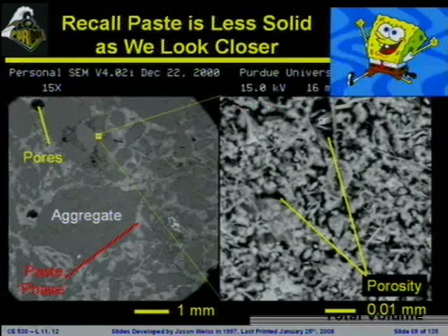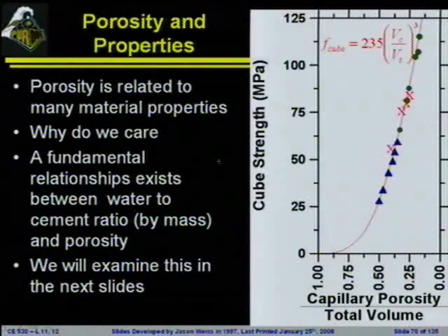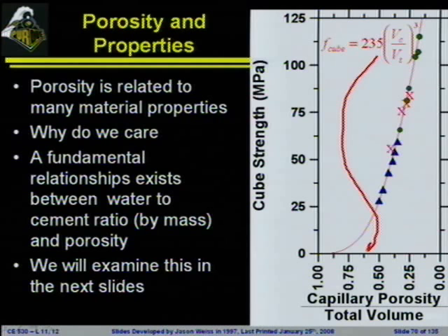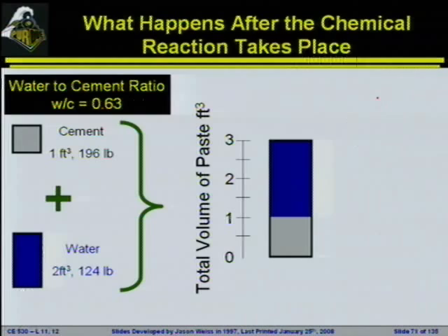porosity. All right, so we're remembering that everything is porous, we're remembering porosity is going to be related, and we're remembering that the strength is related to the volume of the pores over the total volume. And one of the things that I will point out when you look at this equation, because I got a question on this, is you will notice that the x-axis goes backwards, so you actually need to take that into consideration when you use that equation. It starts out at a value of 1 and works its way back to 0, so it's actually 1 minus this entire thing.